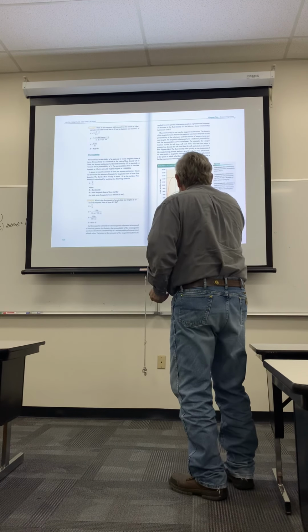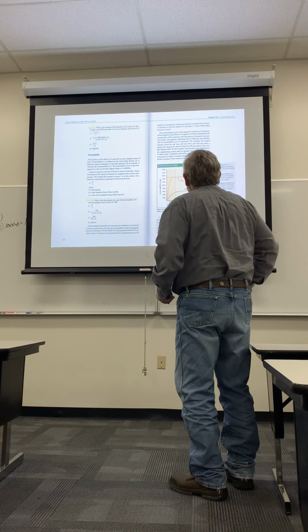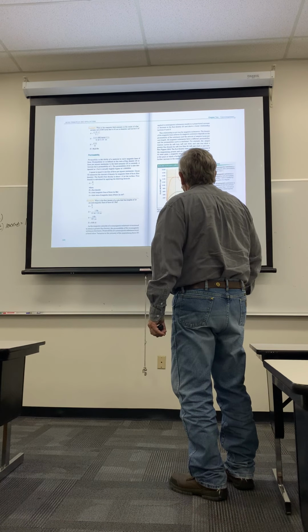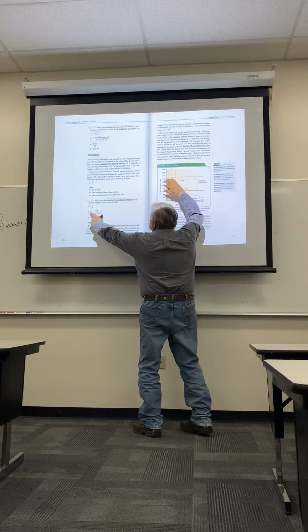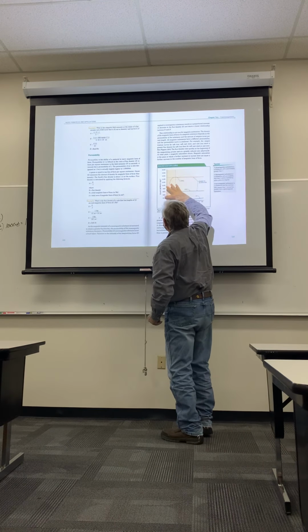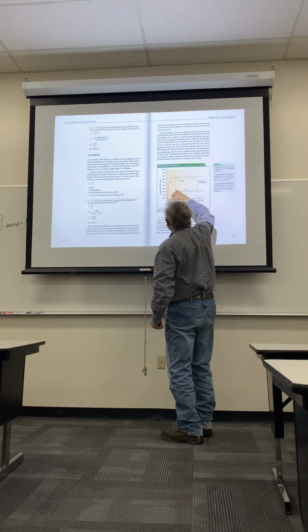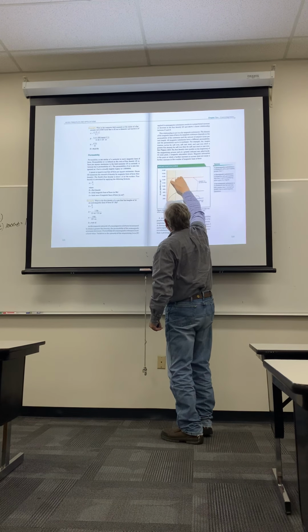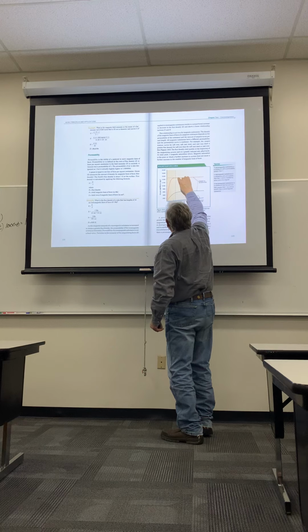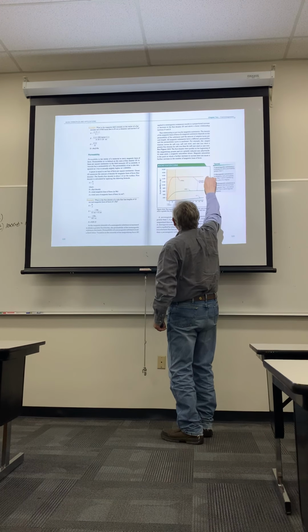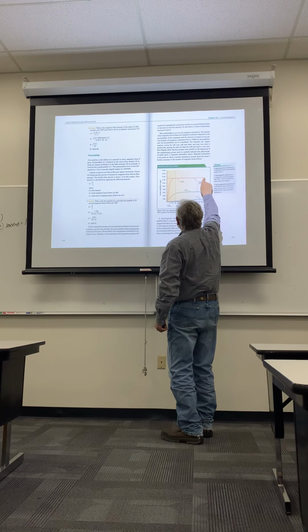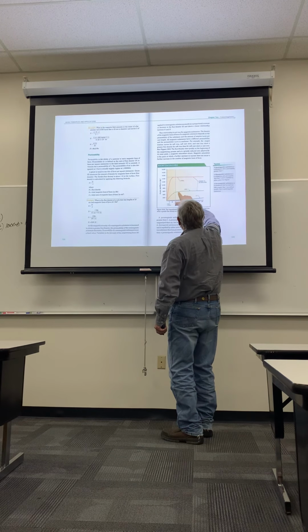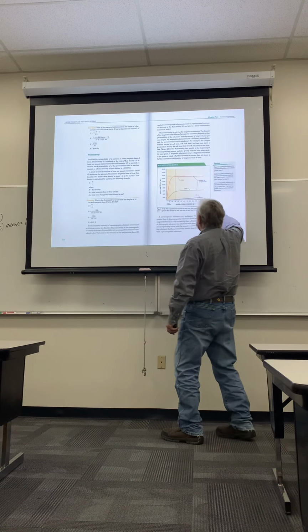Okay, so now let's look at this magnetization curve. We looked at this once before. We talked about the flux density, which is how much gauss there is. So when you induce a current into something, and the current goes up, the magnetism of that material goes up until it reaches a point at which it's saturated. It can't take any more magnetism. Steel has a really high ability to absorb flux density. Iron is not quite so much, and then air is even lower.